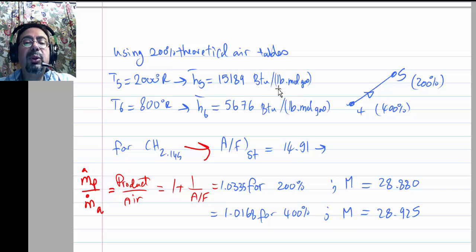So it's BTU per pound mole, not BTU per pound, or basically BTU per kilomole, not per kilogram. So I want to convert between kilomole and kilogram. What is the conversion? Molecular weight. What are the units of the molecular weight? Kilogram per kilomole. How did he calculate this?